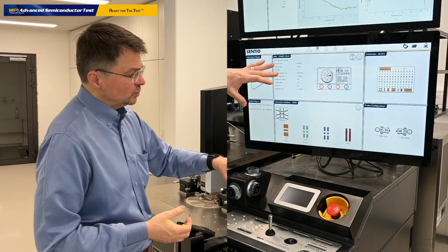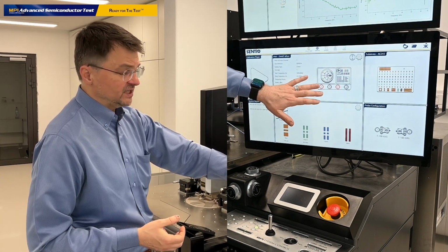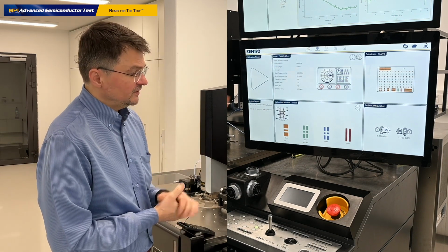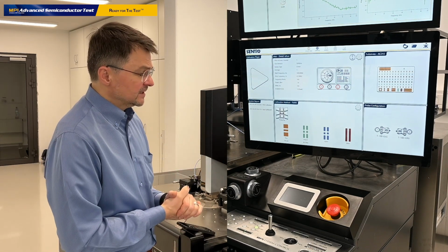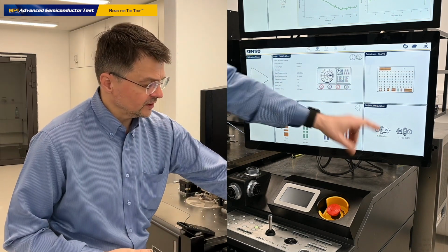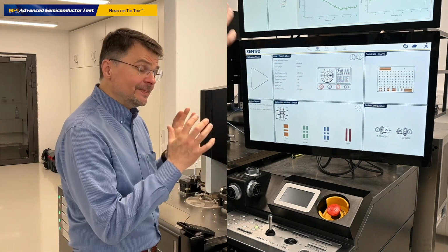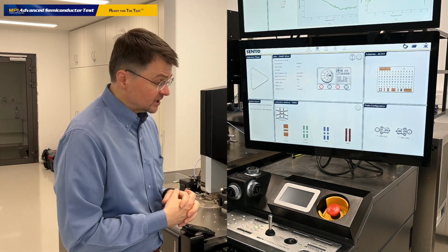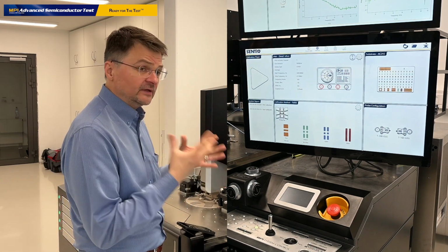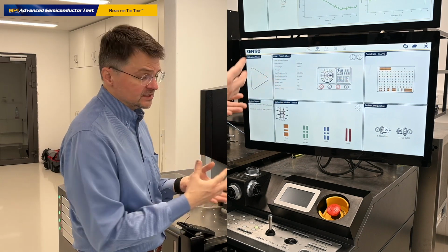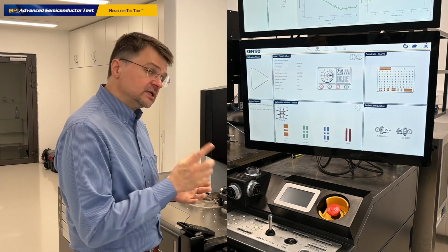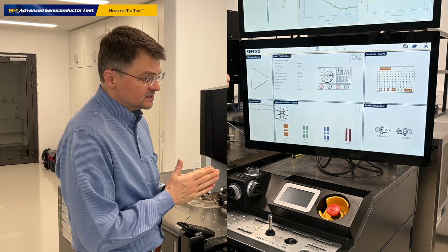We have a widget which gives us a snapshot of the current settings of the network analyzer. This is the ZNA 67 GHz four-port VNA that we currently have hooked up to our system, and it's configured for port 1, port 2 measurements, where port 1 is on the left hand side and port 2 on the right hand side. That is pretty much the initial setup of the Calibria graphical user interface, and it helps you to see what you currently have and make sure that the current settings, which are out-of-the-box settings, are the same as what you really have on your system. I already see one mismatch in the setup.